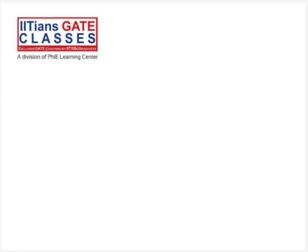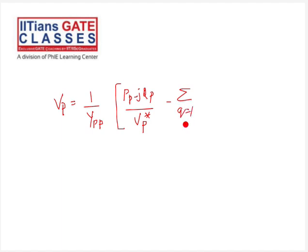So finally, if we substitute that in the equation, we get VP is equal to 1 by YPP into PP minus jQP divided by VP conjugate, minus sigma Q equal to 1 to N, Q not equal to P, YPQ VQ.